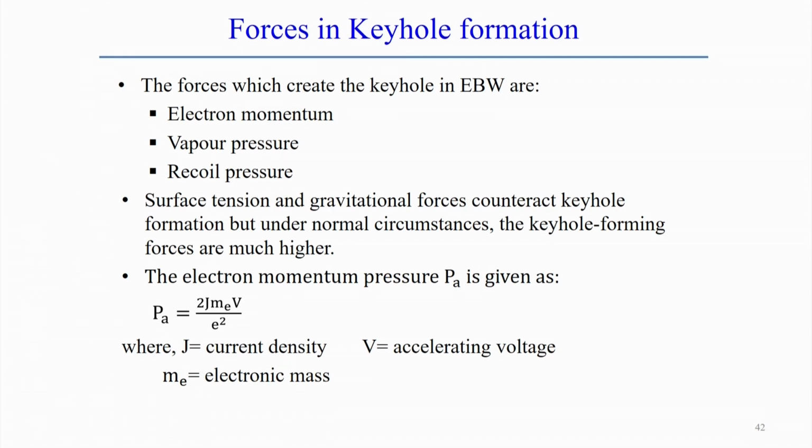So, of course, the keyhole will be open depending upon the magnitude and direction of these two forces, which decide whether the keyhole will be kept open or can also be closed. That can be better explained in terms of how these two forces are balancing with respect to each other. In this case, the keyhole forming forces are much higher, so the keyhole keeps open during the process itself.